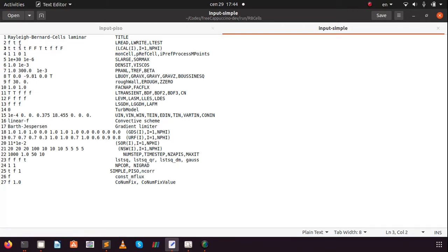The first 3 are reserved for velocity, the 4th is for pressure, the 5th and 6th are for the two equation models for turbulence, the 7th is for temperature. So we have false for solving two equation models in turbulence, and we have true for temperature. This is for modifying viscosity, then concentration, electric potential, and so on.